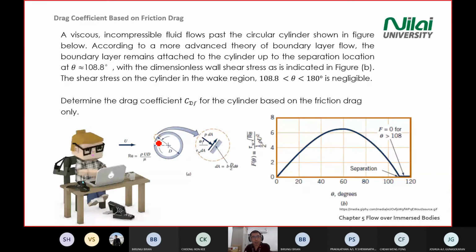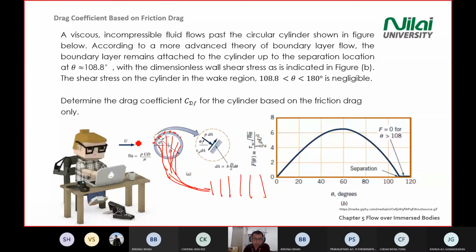If you conduct this experiment in the wind tunnel, you can collect the forces or pressure at each point. You have a cylinder body, you drill holes on the body, and you plug tubes into a pressure gauge, for example points 1, 2, 3, 4.